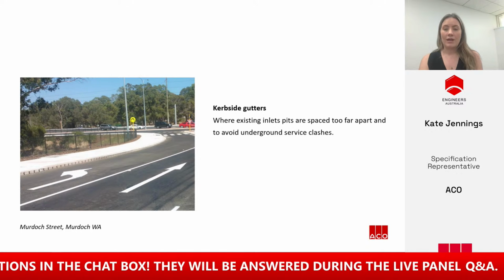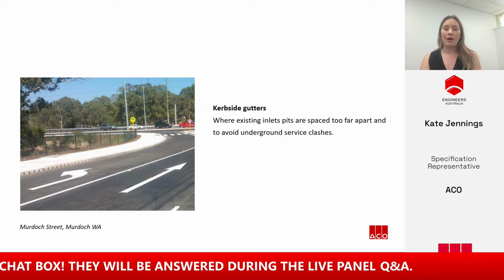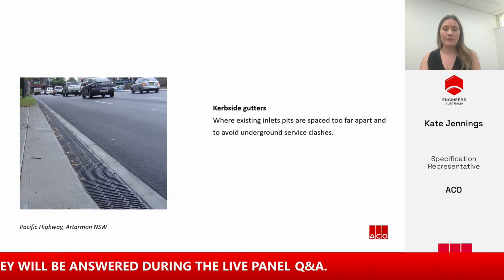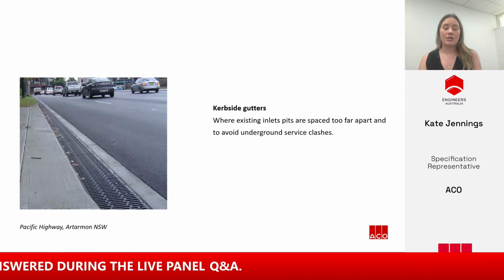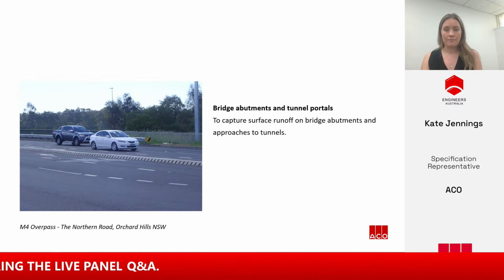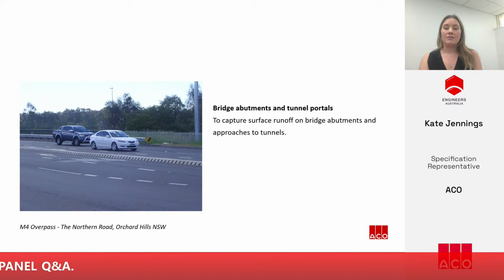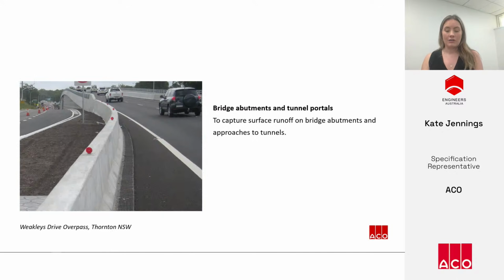In curbside gutters where existing inlet pits are spaced too far apart, slotted curb drain could be used. Or again, a graded trench drain solution could also be used. Also, on bridge abutments and tunnel portals, you can again use a slotted curb drain or a graded trench drain solution.